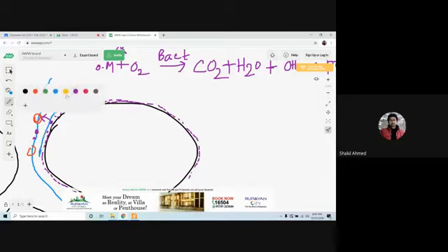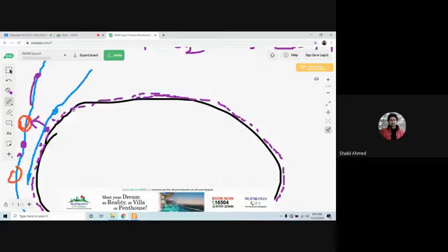Since this layer is gelatinous, it actually adsorbs new bacteria cells. Also, if you have smaller particles here, these also get adsorbed here. That means they are being removed.